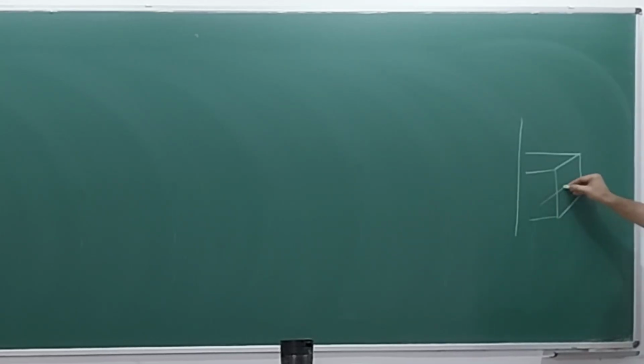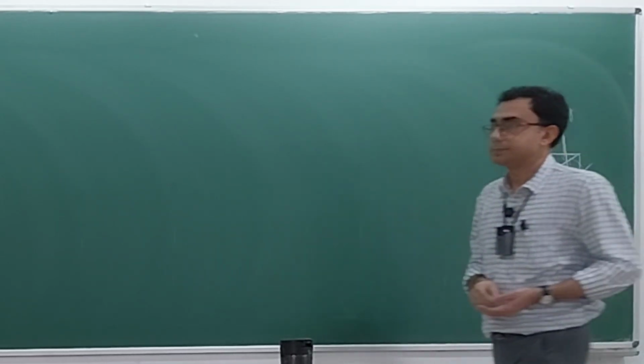Here the neutral axis was like this, your loading was like this, and your moment was like this. This moment is about what axis? It is literally about this axis. Let this be the y-axis and this be the z-axis, and everything will become clear. So this force is along Vy and the axis is along Iz.